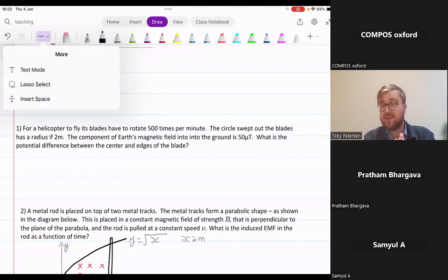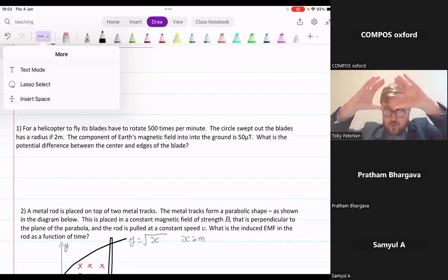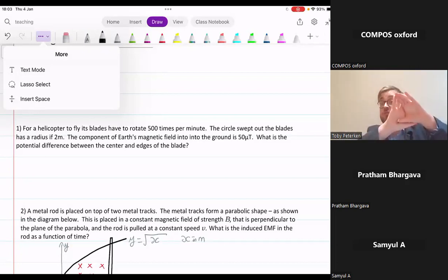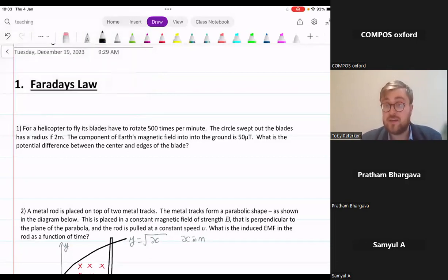There are two ways the magnetic field through that loop can change. Either the magnetic field strength is changing, or, say, the loop is changing size. The loop starts small, so only a small amount of magnetic field can get through. As the loop grows and grows, more magnetic field can go through. So in that case, a current will also be induced. A voltage will be created around the loop and a current will flow around it.